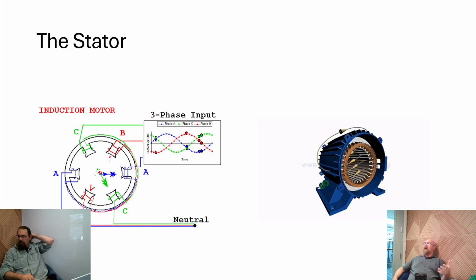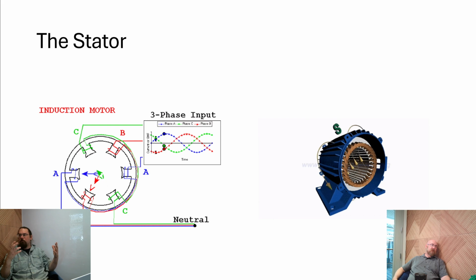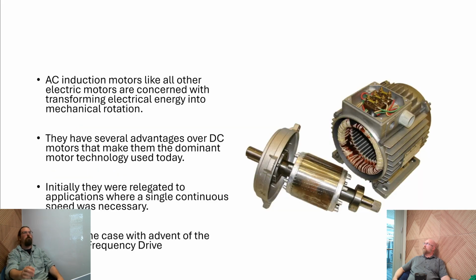On the diagram on the left, you have the three offset 120 degree phase angles of the three phases, and you can see what is happening to the magnetic attraction to these different poles, which is what you see there in the middle. They grow as current peaks on each one. This behavior is what generates this effective rotating magnetic field in the stator. And we use this in combination with the rotor to actually make this work.